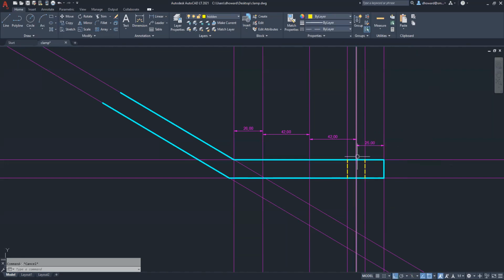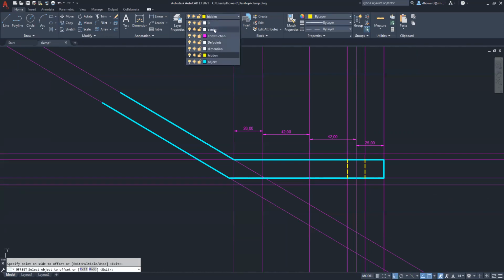When you're drawing, how far is that going to stick out? Well, 1/4 of an inch, right? So what is 1/4 of an inch in millimeters? It's 25 divided by 4, which is about 6. So let's just do that. I'm going to offset this construction line 6 on both sides, 6 up, 6 down. And now I can draw that center line accurately.